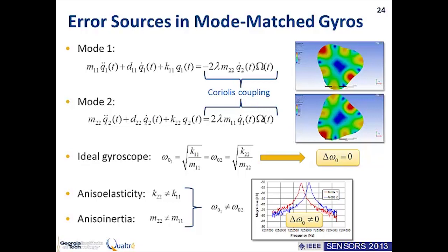Because not every single node in your device contributes equally to that mode shape in particular. If it was, for example, a translational mode, then obviously all of the mass contributes to the motion, so your effective mass is basically the volume times the density, but in resonant type of structures, that's not the case. But anyway, you can basically calculate that by using vibration analysis.